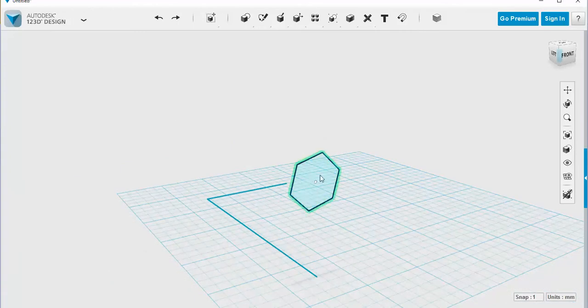So remember, we've got our hexagon and we've got our path here. This hexagon, we're going to call it a profile because we're going to stretch this hexagon all the way along this path. Getting close to the end of class, so I'll just show it once more. I'll upload this afterwards so you can see it. We'll go to Construct and then to Sweep.